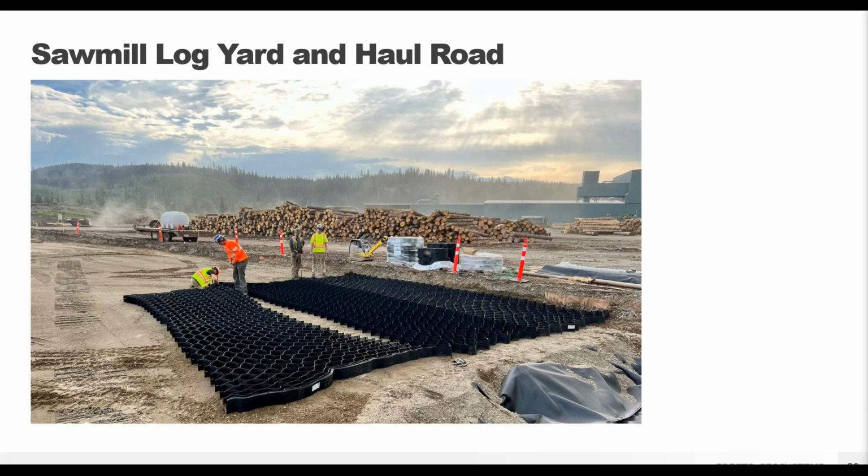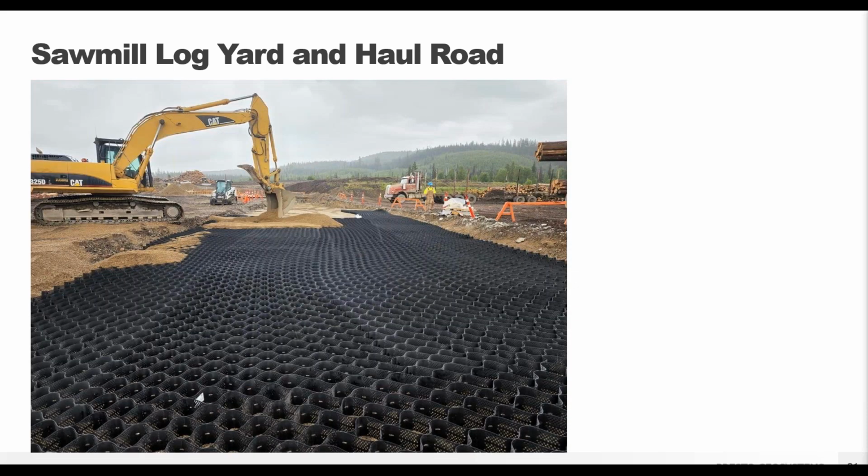So think of walking through the snow: your single foot is going to punch through the snow. It's going to be hard to get back out. You wear a snowshoe, it helps spread the load. You don't sink into the snow. The same thing happens with the GeoWeb system. By spreading out the load, including that geotextile underneath, you're spreading out the stress on the subgrade. You're not going to get punching failures. You're not going to get those shearing failures into those really soft subgrades. That allows you to have this load support where otherwise you might not be able to. And so the GeoWeb system does provide a strong reinforcement layer for those constant heavy loads.